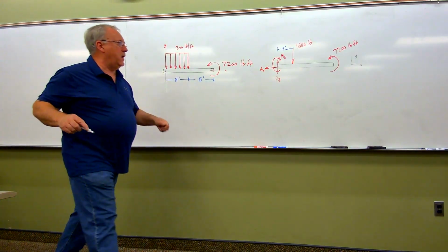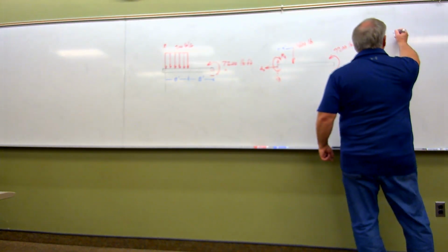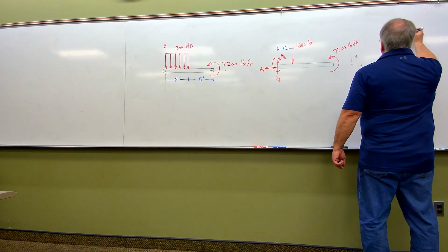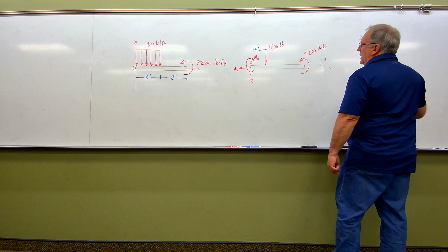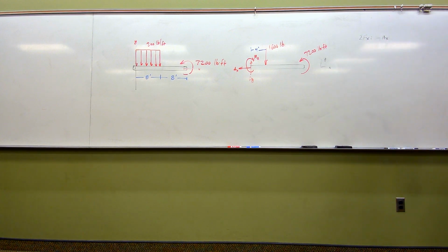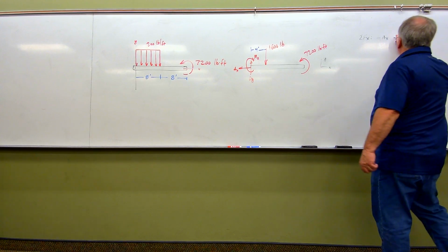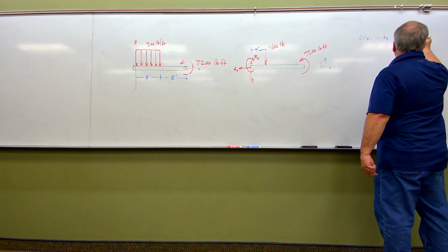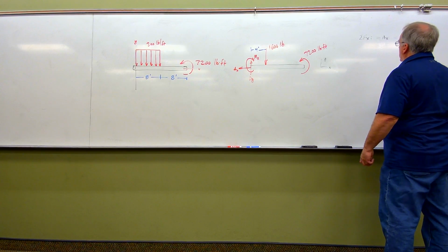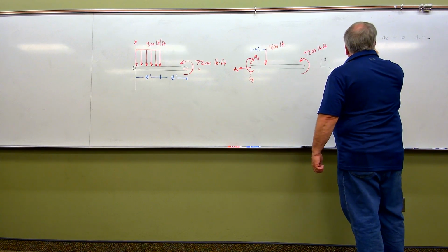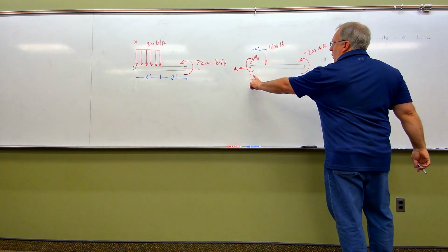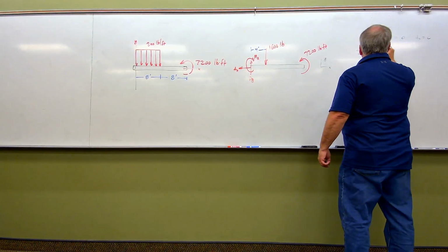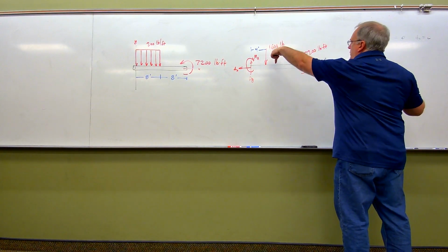Let's sum the forces now. Folks, if I sum forces in the x direction, I see that I got minus AX. And even though that's a busier looking free body than we're used to seeing, there are no other x direction forces on there. So that's equal to 0, meaning that even though we drew AX, AX is therefore equal to 0, nothing new. Let's sum forces now in the y direction. Here we have AY drawn in the positive direction, minus 1,600.